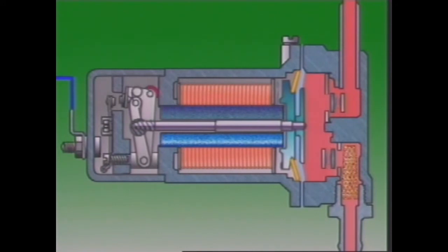When the engine needs less fuel, pressure builds up in the fuel lines to the carburetor and reduces how much fuel is delivered. Some carburetor-equipped vehicles with electric pumps have a safety switch that prevents the pump continuing to run if the engine stops.